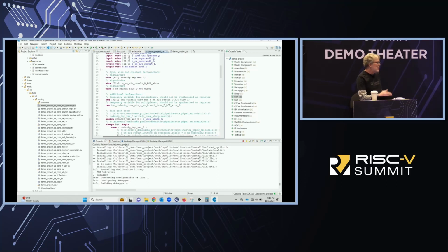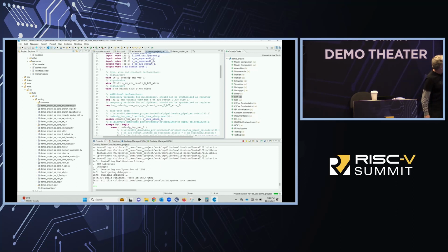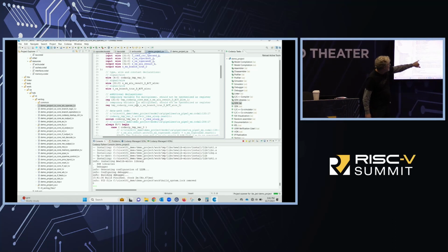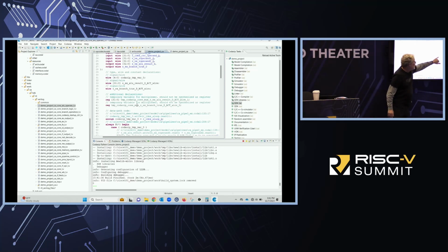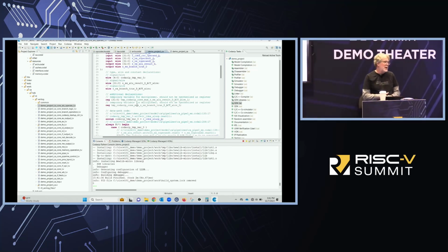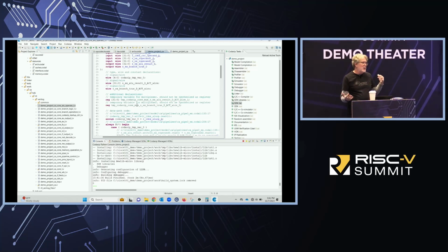and this is what Barath was talking about before, you can see where it clearly indicates exactly where that line of RTL came from. So it says it came from CA pipeline 3 execute stage and on line 135. So it's really easy to go backwards, right? If you're looking at your RTL and you want to understand where it came from, you can go backwards. So that's a really key functionality, the comments that get generated.